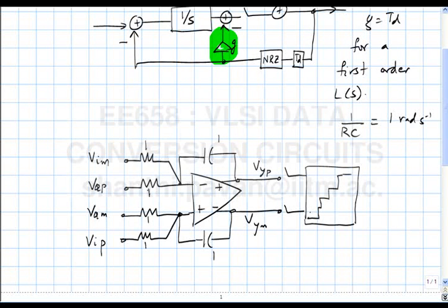You can use a full thermometer DAC, and you can see that the complexity involved in a full thermometer DAC is very small, because typically the number of bits in the quantizer will be 3 or 4 or 2, or if it's 1, of course there is no big deal at all. So the quantizer will basically be the thermometer output of the flash directly driving a thermometer DAC, and in many cases the DAC happens to be a current steering DAC because of several advantages, and the output of the DAC is a current which is fed to the input node of the op-amp.